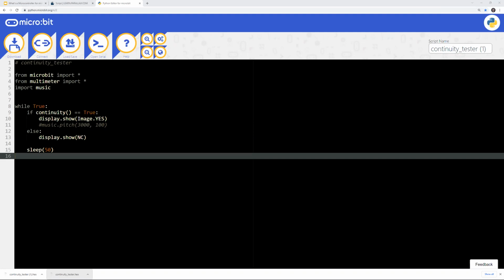Hey, quick question. Can you hear me? Yes. What type of volts should we be getting? About 3.25? Yes. Roughly 3.25 is good. 3.3 is in theory what it's supposed to be, but it's not going to be exact. You know, plus or minus 0.1 volts is good, and 3.25 is right in there. Just like a resistor, plus or minus. Yep. Thank you. You're welcome.